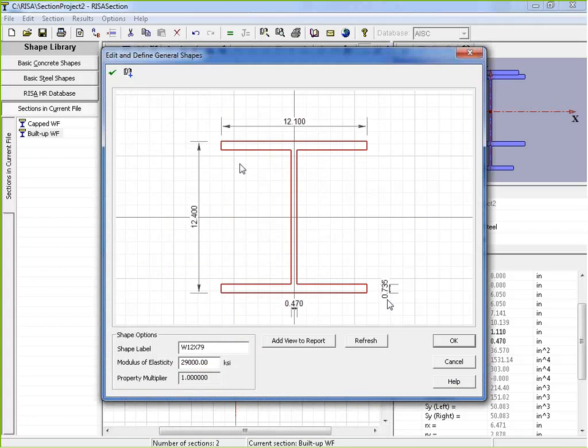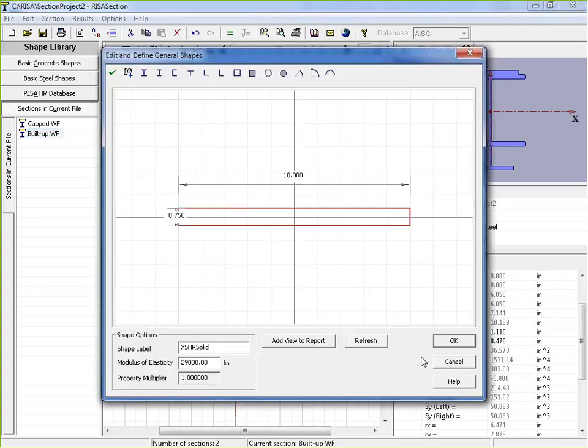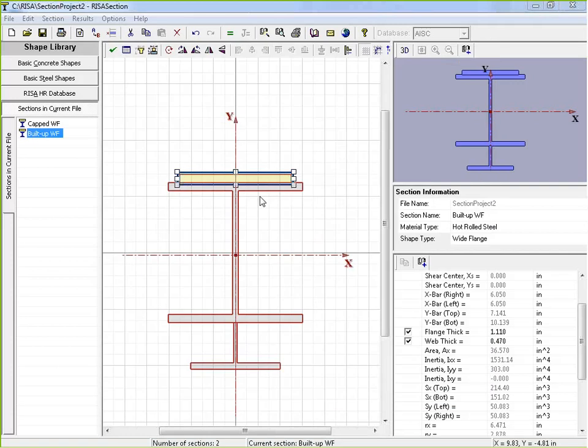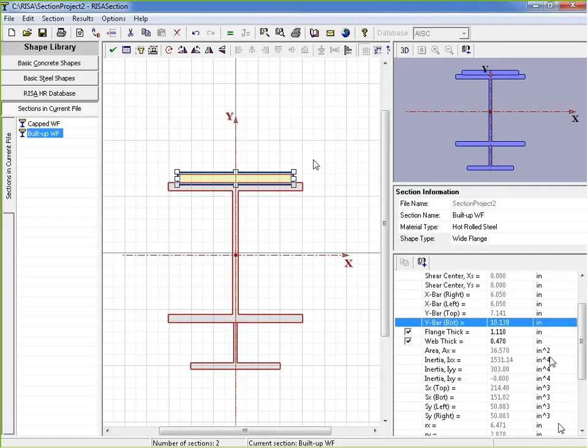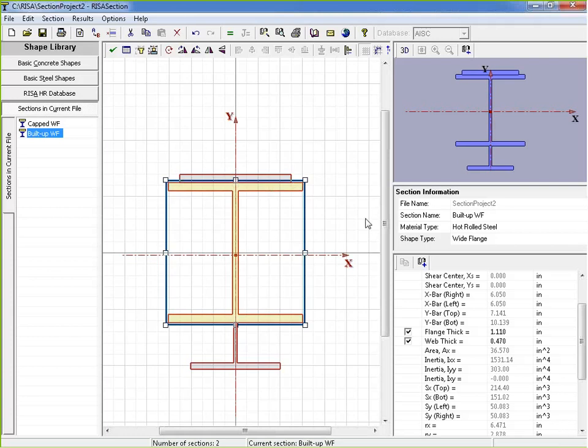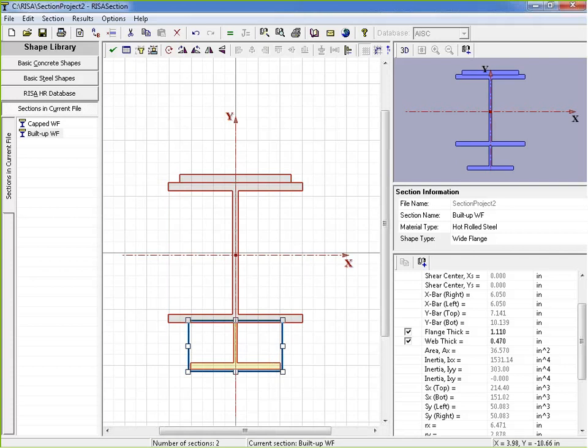We're looking at 0.735, and we're looking up here at 0.75. So it's kind of a combination of that, and an average is probably pretty good. If I took the top two, that thickness might be a little bit higher, but the average is kind of working it out, especially as we look down the lower portion. But I can override that if I wanted to. I can uncheck this and override it if I needed to have control over that.